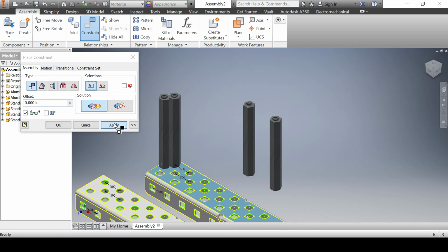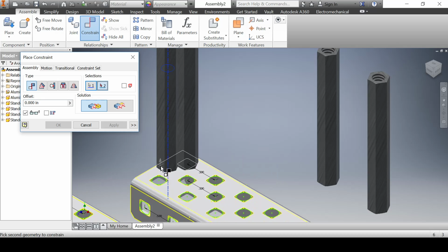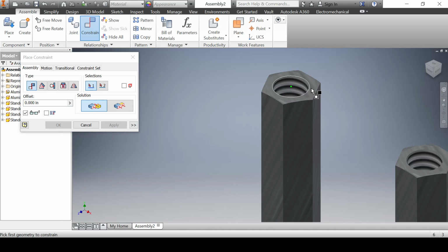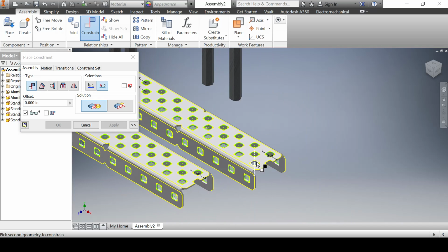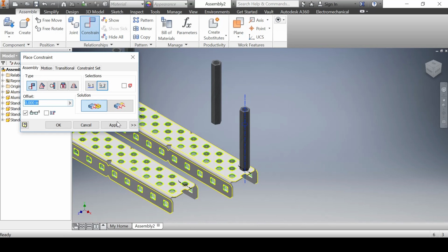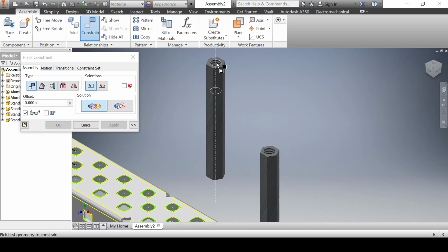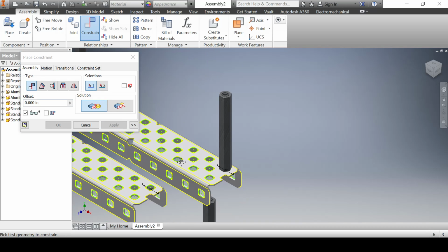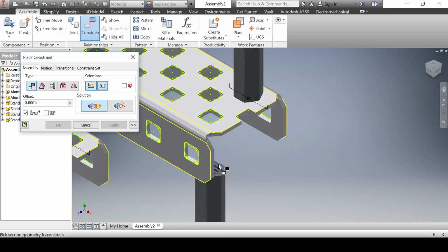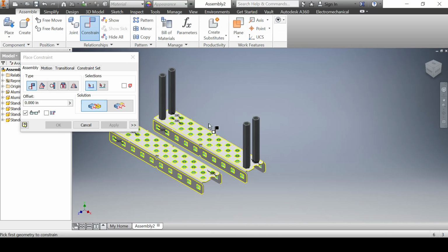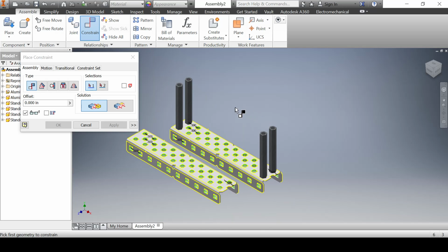Apply there. I'm going to mate that axis with the circle there. I want to get my surface first. Now notice I'm doing the surface first and then the axial second. This is not completely necessary. It's just my personal preference. You could do the axis first, but you can see now it's kind of down there. It just takes a little more time sometimes. Boom, there's our part. All right, so we got our first few steps down.